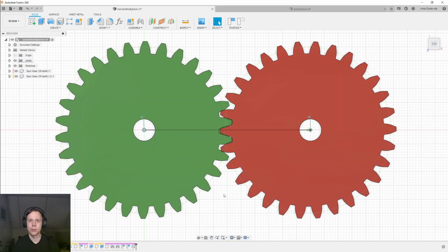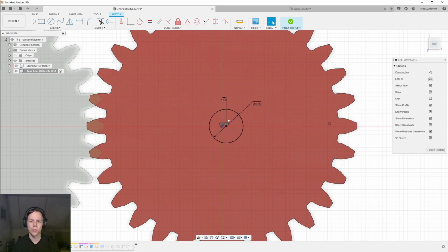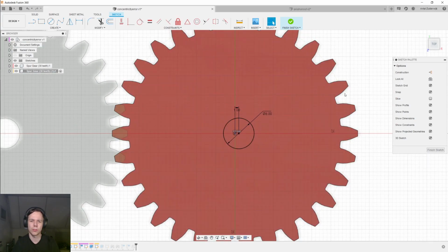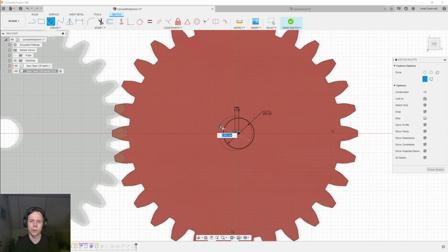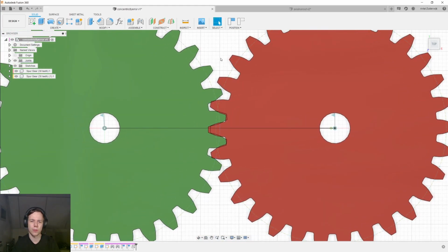I've talked a lot in this video about the distance between shafts and why it is important to get that dimension right. But there are two other errors that you can make with the shafts that lead to many of the same problems. In this first example, I'd like to show you a concentricity error, sometimes called a radial runout error. And so if I look at this hole here through this gear, I have made it a millimeter off center. So the hole should be over here at the origin, but instead it's a millimeter to the side. And this leads to two problems at the same time.